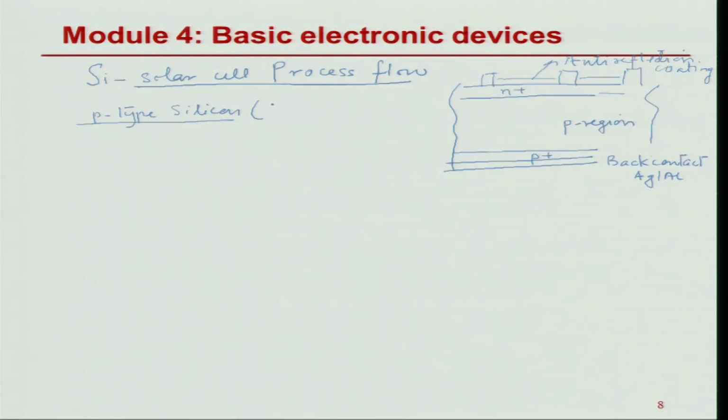If I take what we call electronic grade silicon, which has of course very high minority lifetime and other things, then that is going to be very, very expensive, and the lifetime of minority carrier is in the range of 20 to 200 microseconds. But that's for electronic grade one. One can make solar cells using that, but the cost of that material is very high.